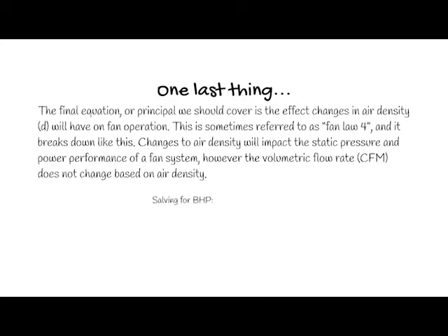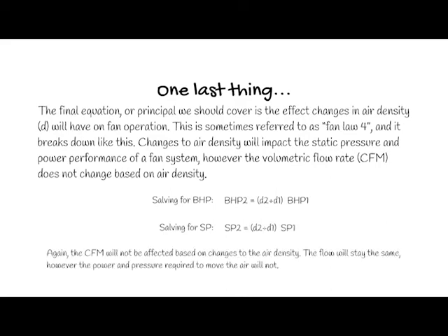If we solve for brake horsepower 2 equals density 2 divided by density 1 times brake horsepower 1. If we solve for static pressure 2 equals density 2 divided by density 1 times static pressure 1. Again, the CFM will not be affected based on changes in air density. The flow will stay the same, however the power and pressure required to move the air will not.